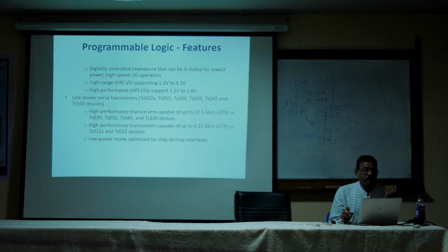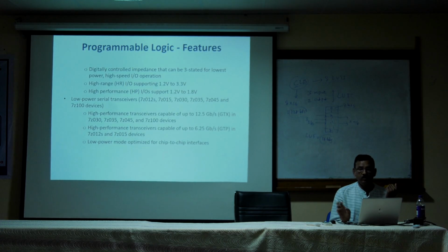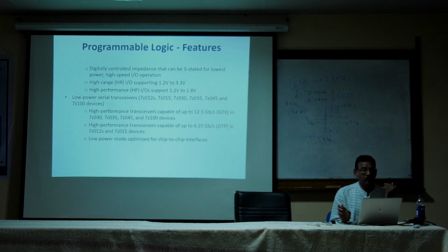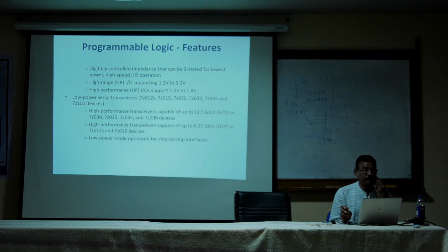High range IO supporting 1.2 volts to 3.3 volts, high performance IO supporting 1.2 volts to 1.8 volts. That is the IO technology we can use for high range or high performance.